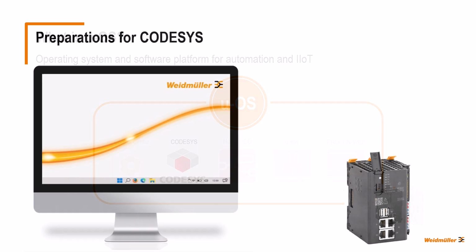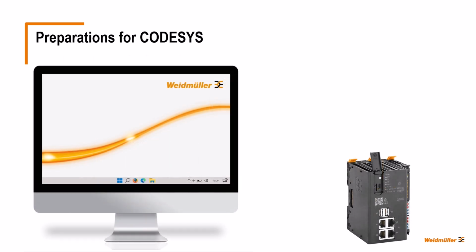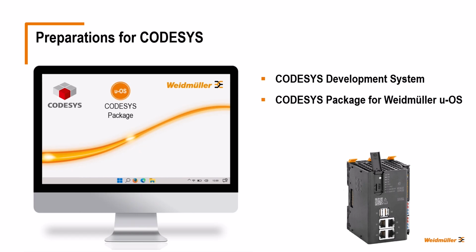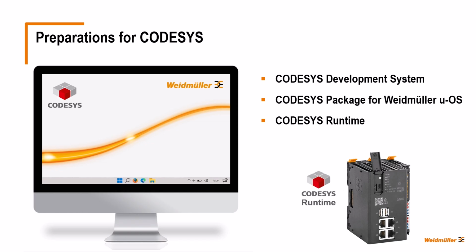This requires some preparatory work. First, we need the CODESYS development system on our PC or notebook. This is used to create the PLC project. In addition, we need the CODESYS package for Weidmüller UOS for the CODESYS development system so that we can use Weidmüller devices in a CODESYS project. Finally, we need the appropriate CODESYS runtime for the UOS device so that we can execute the created CODESYS project there. Let's start with the CODESYS development system.